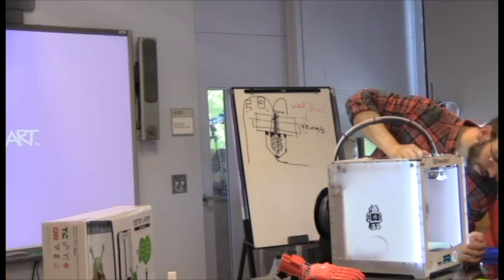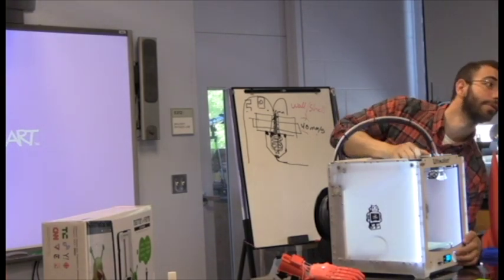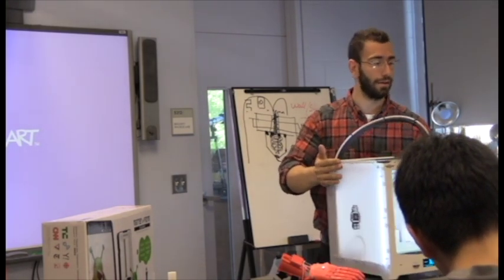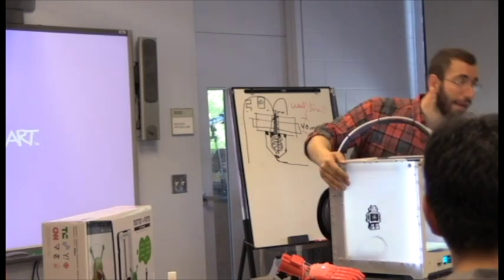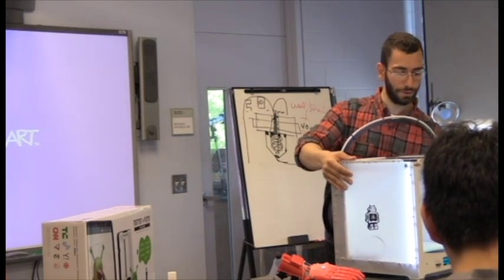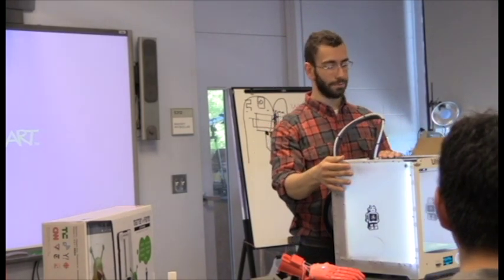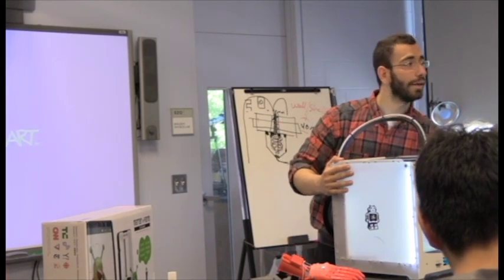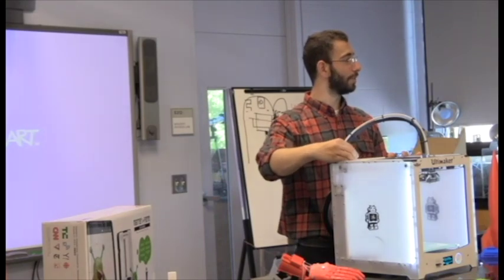Good. Okay, so we're going to go under material. We're going to click on material, which is the other option next to prints. Click on material. We're going to click on change. It's going to go back to 0 on this end over here. The bed doesn't necessarily need to come up. And it goes to the front for ease because usually you will be working here. Every time it does anything, it will always go back to 0 to know where it is.